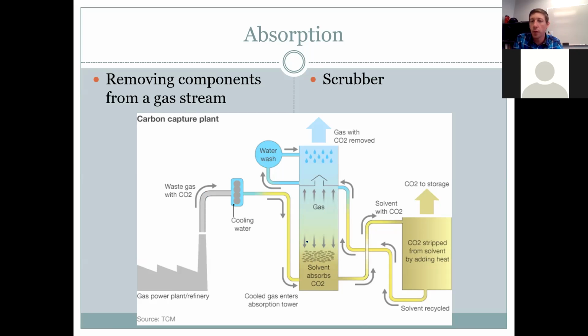This is something that over where we do our labs at the ethanol plant, they don't do, but a lot of ethanol plants do because they're bigger. Where we have CO2, they just emit it out to atmosphere because there's not enough to really do anything with. But other ethanol plants will actually bottle that up and sell that as an inerting gas, or sell it to Coke and Pepsi, or Anheuser-Busch or places like that, where they can carbonate beverages with it. In order to use that, it has to be cleaned up. And in order to clean it up, one way is a scrubber.